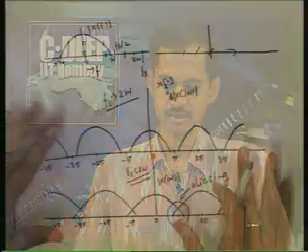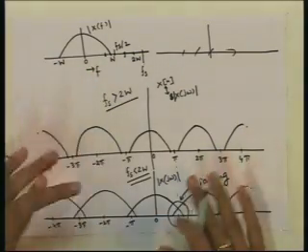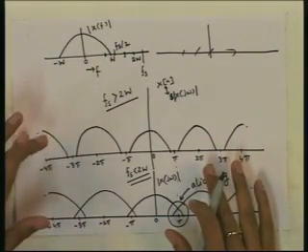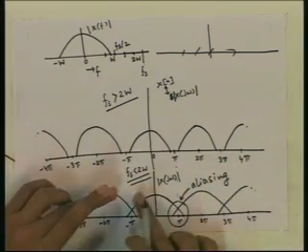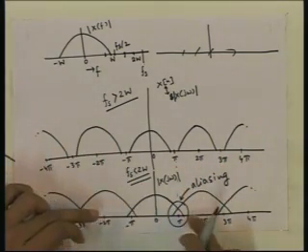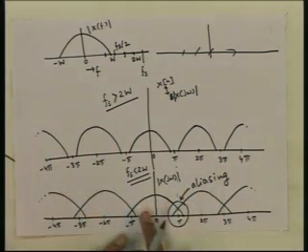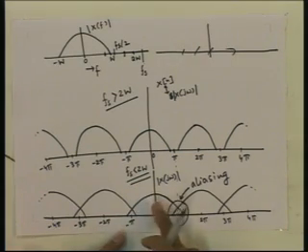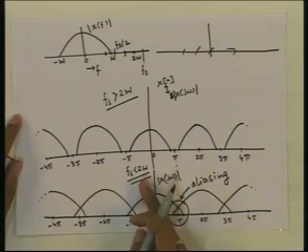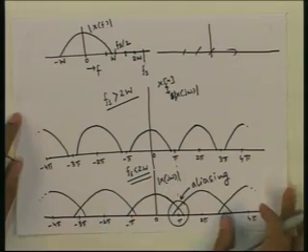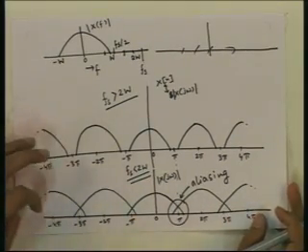But let us also see, here we have seen in the frequency domain why Fs greater than 2W is required for recovery of the original signal, and why Fs less than 2W is not sufficient. It may not be possible to recover the original signal if Fs is less than 2W. We will also try to get a feel of the same thing in the time domain.